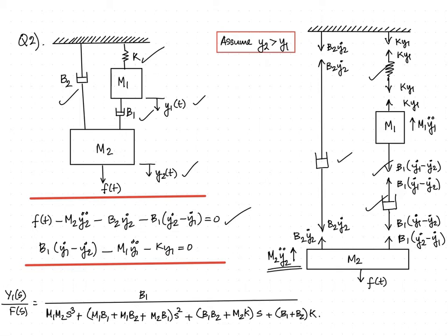Since the motion of mass m1 is marked downward, its inertial force will be towards the top. The spring experiences a tension and hence its reaction on the mass will be towards the top. Finally, we can verify the entire directions by checking what is the effective force on the wall. You can see that it is towards the downward direction. So is the case for the reaction by damper also. Here we have two masses, hence we need to consider two equations with respect to m1 and m2. The two equations are written and finally we can obtain the transfer function once we convert it into the S domain.